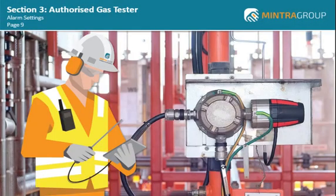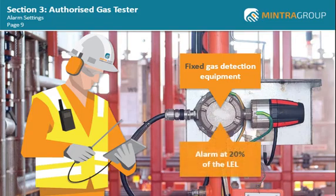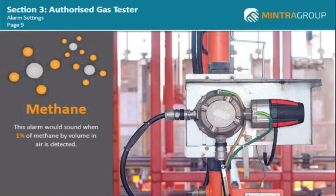Let's now consider what you will see and hear when you are carrying out gas testing. Most critical parts of the plant, which have the potential to release gas, will be covered by fixed gas detection equipment. Examples of this are gas compression areas, which are covered by fixed gas detectors. These systems normally alarm at 20% of the LEL. In the case of methane, this alarm would sound when 1% of methane by volume in air is detected.